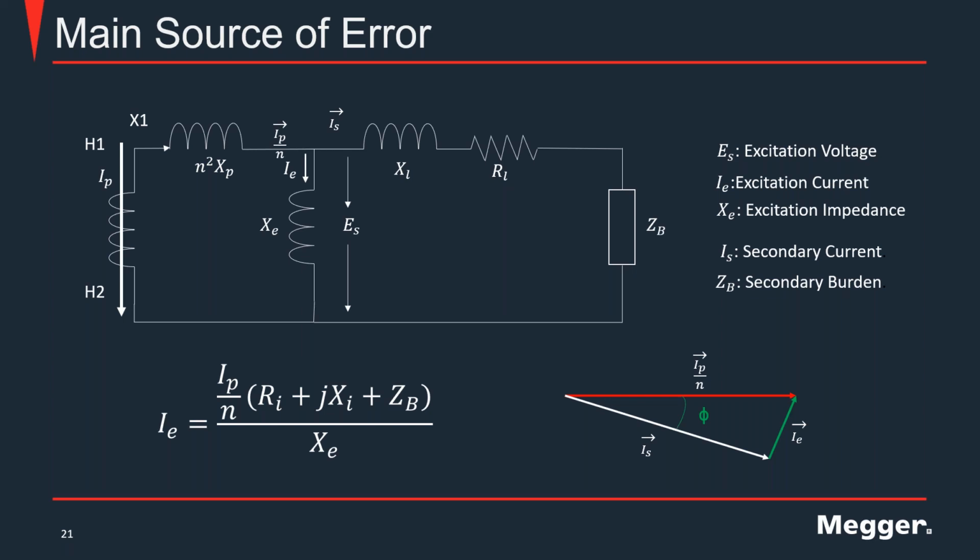So those are the three main elements you have to consider: how much current you are going to measure, what the application is going to be, and what load you are going to connect to it. I'm leaving voltage levels and things like that out of the question in this case. I'm basing my answer on the metering characteristics of the CT.